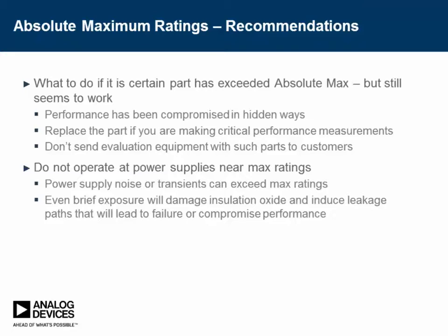So you certainly do not want to operate near the max ratings of the power supplies, because what can happen is that you can get a spike on the power supply because of certain loading, or a spike to the input of that power supply that propagates, and even a brief exposure to excess power supply can cause a part to fail, or to induce the possibility of future failure.